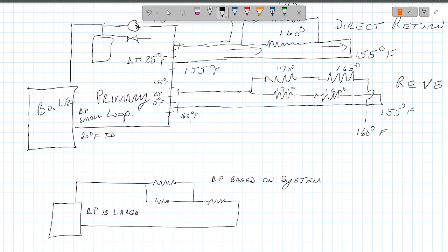Doesn't mean we don't have a pressure loss, but we just push fluid around X number of feet of pipe at what size and gone through how many fittings, it's going to have a pressure loss. But because we brought the fluid back in next to where we had a higher pressure, high P here, and low P there, we are able to keep these two delta P's relatively small. Does that make sense?